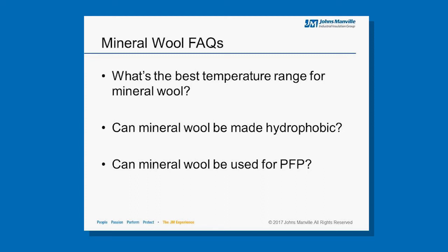Can mineral wool be made hydrophobic? Well, with enough hydrophobic agent, mineral wool or any product can be made hydrophobic. However, again, hydrophobicity is dependent on temperature. At 600 degrees, the hydrophobic agents will oxidize, and at that point in time, the material will no longer be hydrophobic.